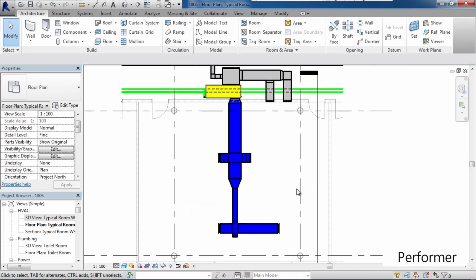So in this lesson, we looked at modifying ducts and duct systems. We looked at ways to select the entire duct system and modify its type. We also looked at the drag capabilities to drag duct components, duct diffusers, duct mechanical elements, and duct segments themselves to new positions. We also looked at ways to actually view and modify the actual duct elements.